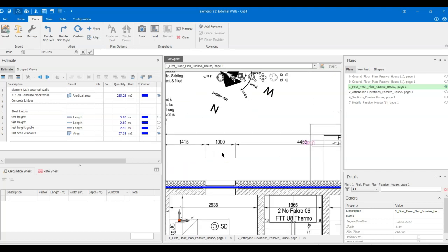Every time you have a window width, to get the head width, you have to allow 225 on either side, because the head extends in 225 on this side and 225 on that side. That's a half block. So you measure up the width plus 2 times 225. So 2 times 225 is 450.